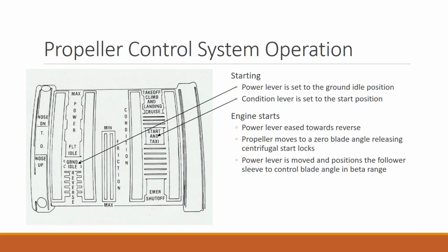The reason you have the third lever in a free power turbine is because the propeller and prop gearbox in the power turbine can spin at a different speed than the core of the engine, the gas generator, and thus you add that third lever to be able to control the RPMs of those two sections separately. Okay. So here they're all the same, they're all linked together, so we don't need a third lever. We can control the RPM and the power using two levers.